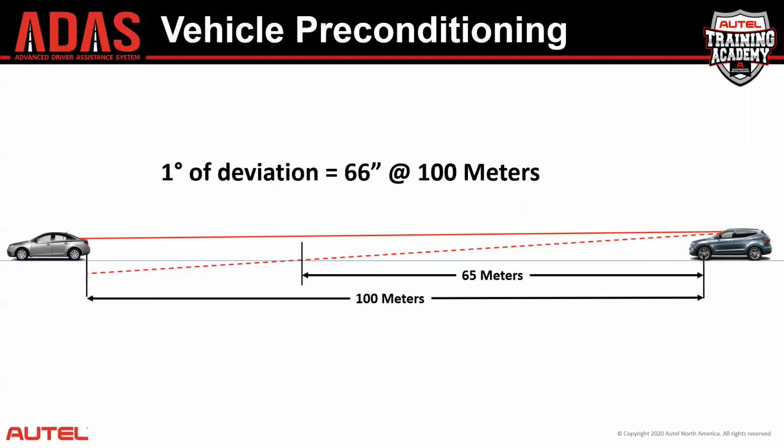Now, if you want to read details about this phenomena, IIHS, the Insurance Institute for Highway Safety, did a study of exactly this. They changed windshields in a bunch of vehicles and they documented the reaction time of automatic emergency braking based on very slight changes in camera position. They found that a change of as little as 0.6 degrees in camera position could cut the response time of automatic emergency braking in half. That's a difference between a vehicle stopping safely every time or a vehicle getting into a collision every time.